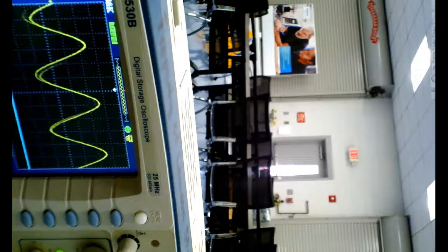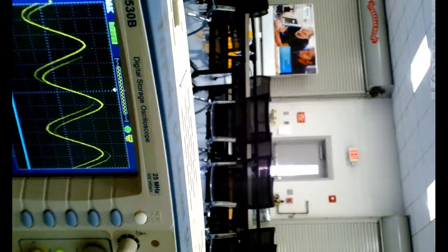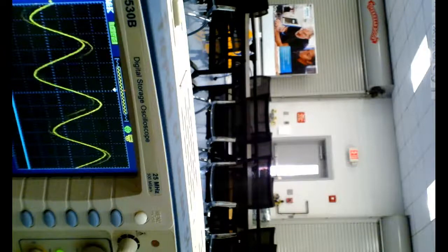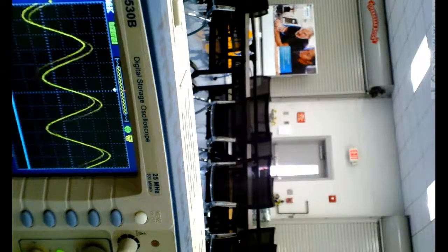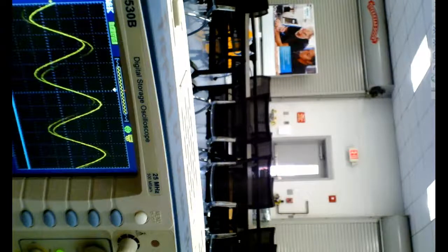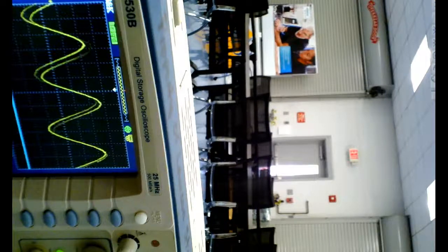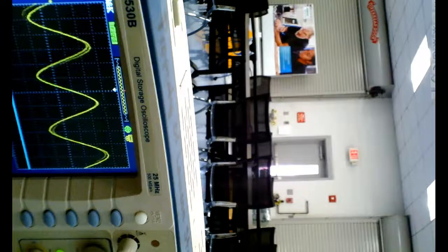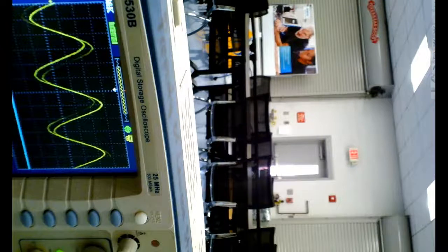But what's nice about capacitive sensors is they'll see glass. Optical sensors can't see glass. They can't see something that's transparent like gas. So capacitors can be designed to detect gas. A lot of your gas detectors that you put in your house are nothing but two plates, using air. And if gas gets in there, it changes the dielectric, and if it changes the dielectric, it changes the opposition.